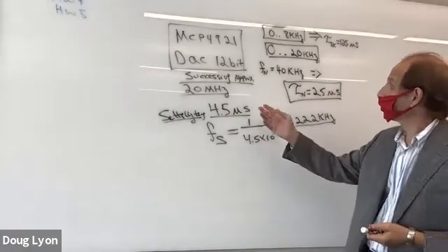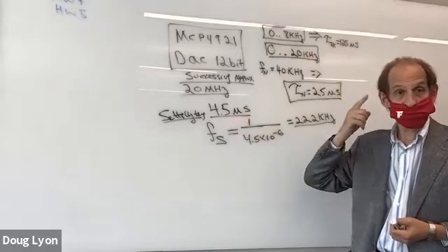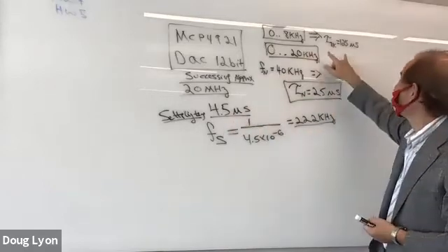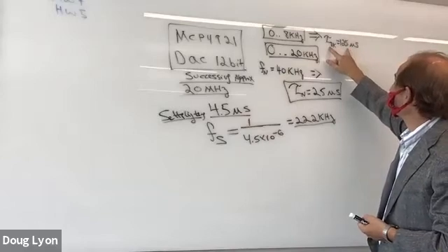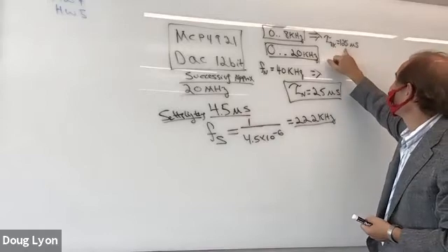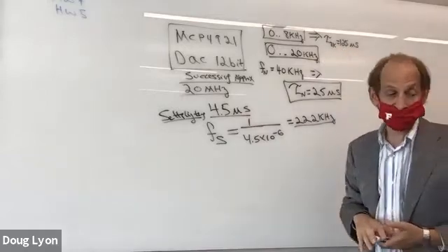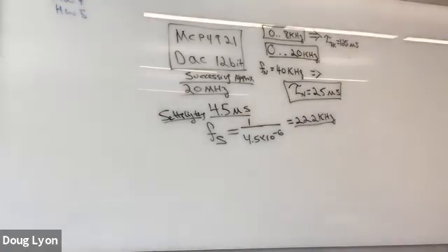We've just gone 2 orders of magnitude slower and have decided that we can do a nice sustained sampling, which will get us out to 4 kilohertz of audio if we sample once every 125 microseconds. That's pretty good.